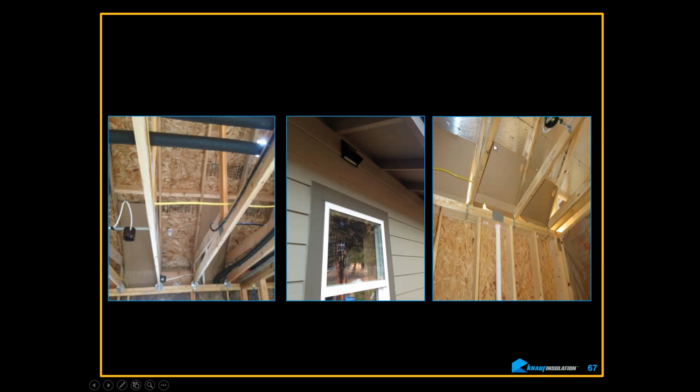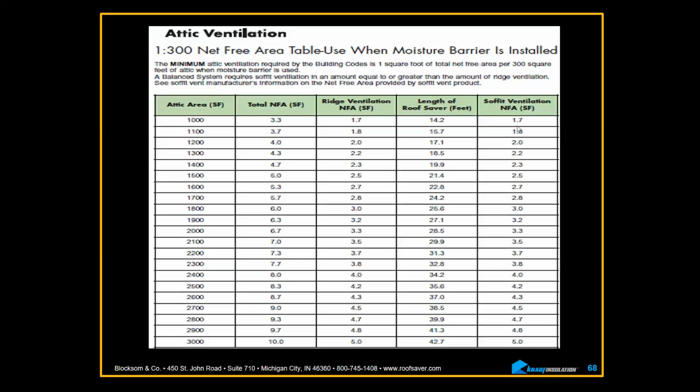You can see it here. These are not stapled correctly. When these get wet, they will fall down. And not to mention that they've got holes in them, and they got a wire popping through. They got everything wrong here, as you see. You can't use a hammer tacker to put these on. You need a heavier staple than that. You need more of them, and you've got to staple from here to here. Two up here and two down here don't work. They do make waxed cardboard, believe it or not. You can buy it. It's a couple of cents more per board. Or you can use the plastic molded stuff.